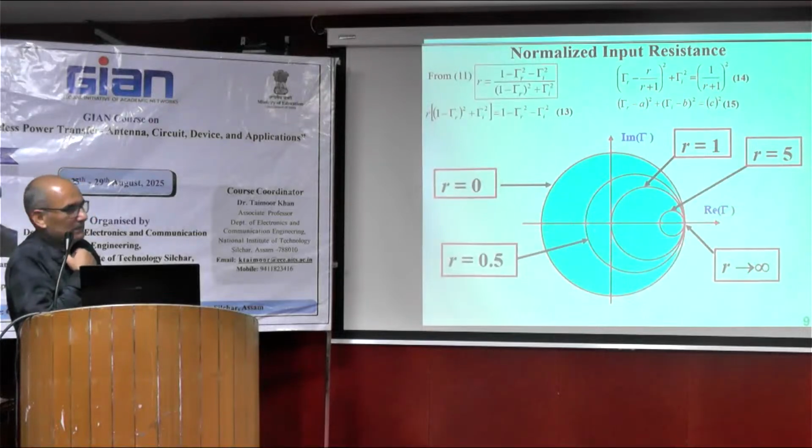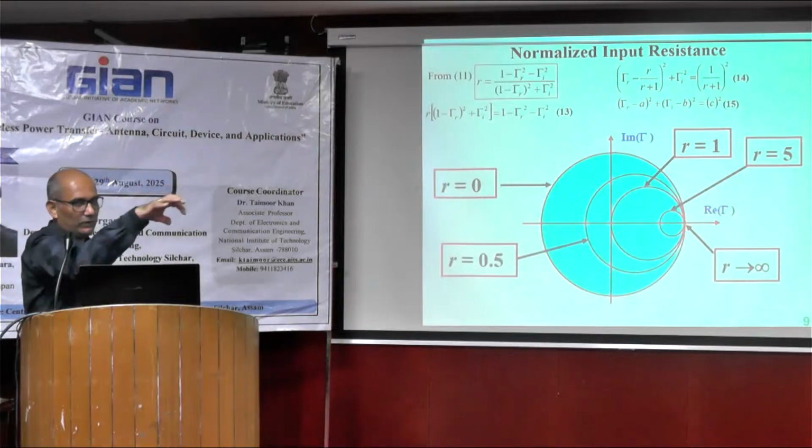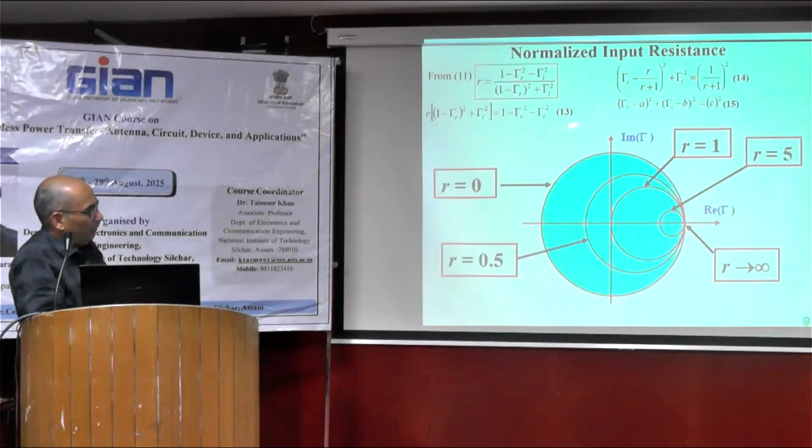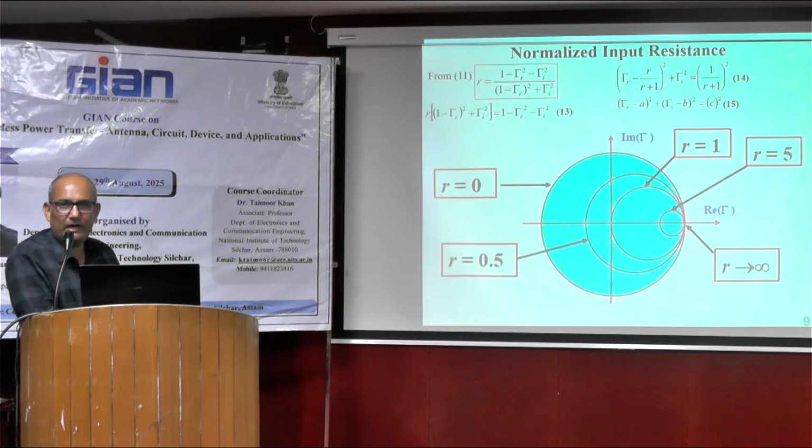on this x-axis. As you reduce that value, or go toward the higher side and do the reverse, then at the extreme point R equal to infinite, you will get a 0 radius circle. It means all these resistive circles exist centered on the x-axis. Then the outer one is the R equal to 0 circle, and this one is the unit circle,